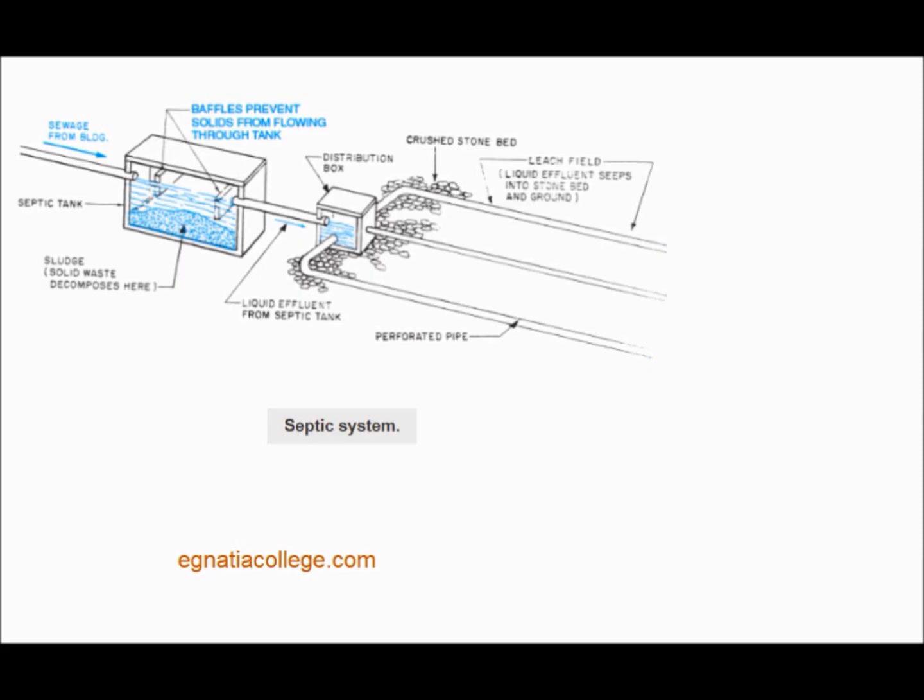The workers who install the sewer must be able to determine the elevation at which it passes through the foundation and the pitch of the line outside the building. The sewer line may be shown on plans as a solid or broken line. Although it is usually labeled, this is not always true. When the sewer is not labeled as such, it can still be recognized by its material, pitch, and ending place. In light construction, the sewer is usually the only 4-inch pipe to the building. Also, the sewer is the only line with the pitch indicated.